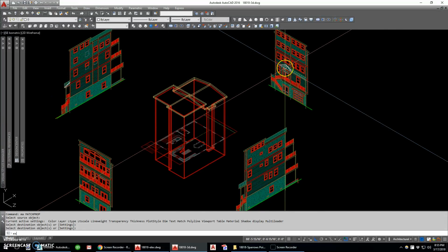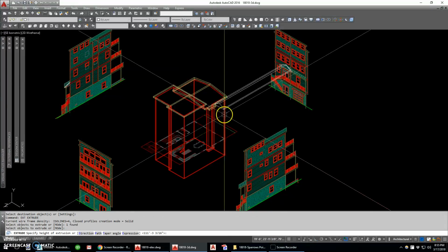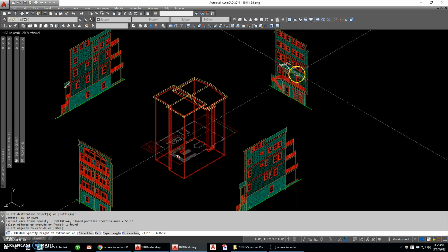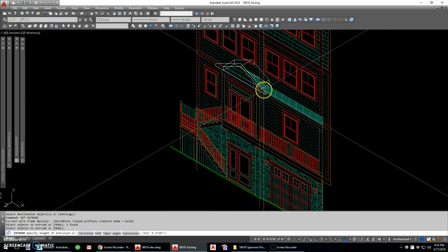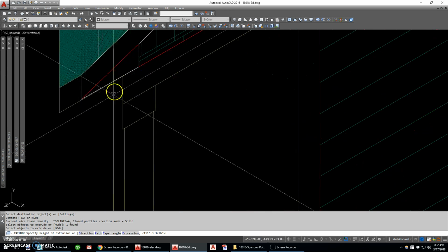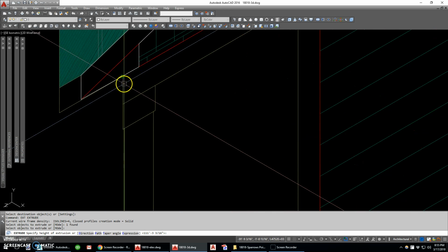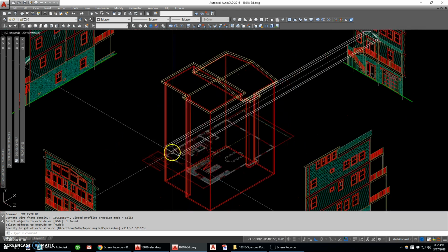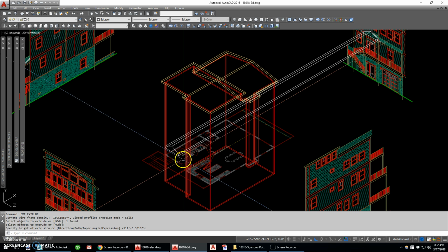Now I'm going to create this front wall. Again, I'm going to extrude it. I'm going to assume that that front wall is flush with the beam, I guess. Yeah, we'll do that. So I'm going to use the front of the beam here as my reference and extrude it to there. Now in this case, I don't have a good reference drawing to slice that 6 inches thick.